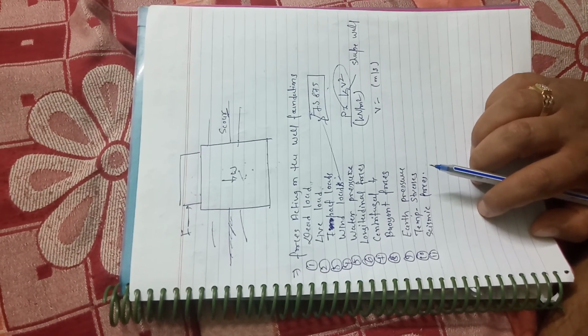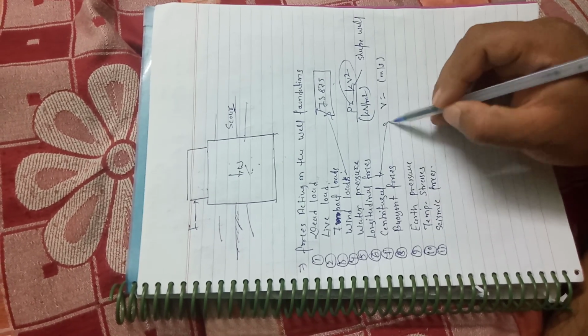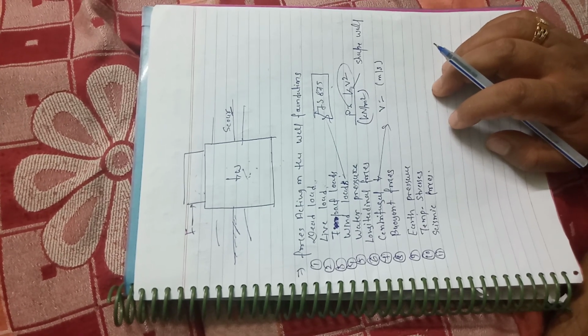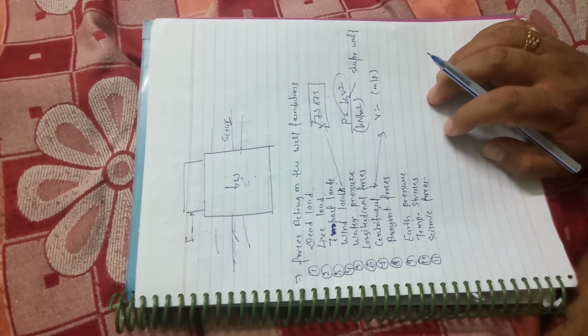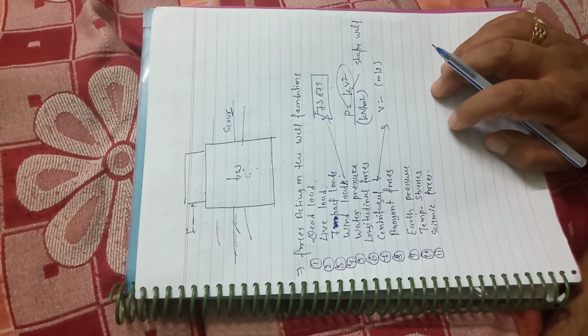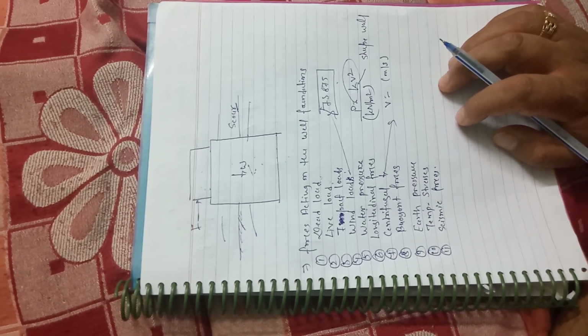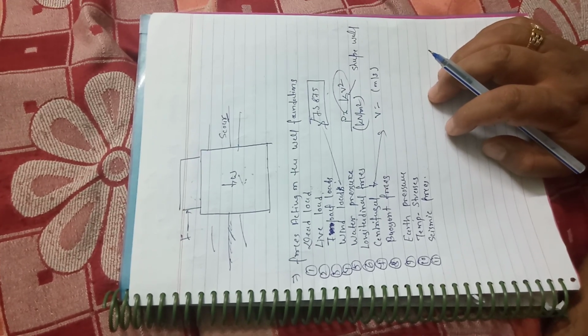Next is centrifugal force. The centrifugal force is mainly considered when the vehicle moves on the road surface of a bridge. Only here we calculate centrifugal force, because the centrifugal force is transmitted through the bearing if the bridge is curved in plane. Next is buoyant forces.